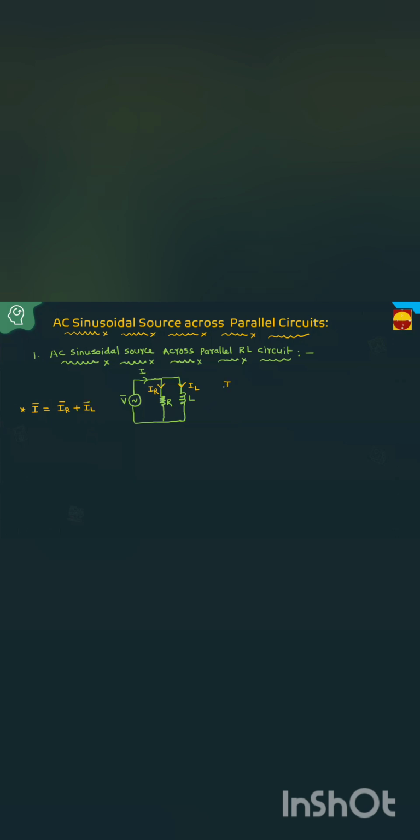Then how to write IR? The current through the resistance is V by R, that is V by R at angle of 0. Then what is the observation here? IR is in phase with voltage, the angle is 0 degrees. IR in phase with voltage. These observations are important to draw the phasor diagrams.